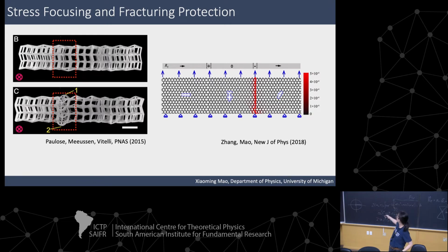So then in this work from my group, what we tried to do is to see if we can use this type of idea to control the fracturing of materials. So if you go to the full nonlinear regime and let the material become damaged, what happens? So what we do here is a numerical experiment. We have a 3-domain lattice such that I have a state of self-stress domain wall here and a zero-mode domain wall here. These arrows are the topological polarization, okay? And then I put this lattice under stretch. I just stretch the top and the bottom and see what happens.